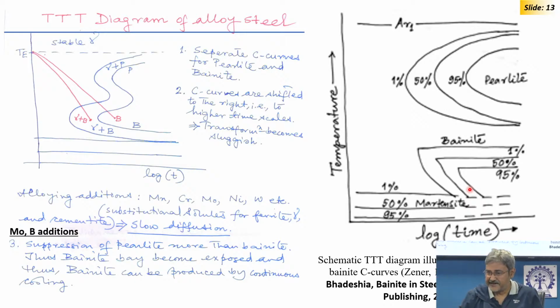Okay? And defects, if you go by Olsen and Cohen's paper, are also dislocation dissociations kind of things. So, some dislocation partials are involved even in the nucleation of this kind of phases. To nucleate this process, it is a very fast process.